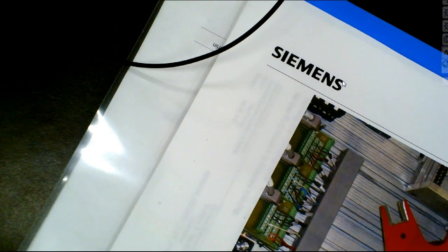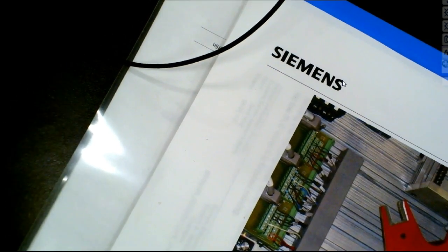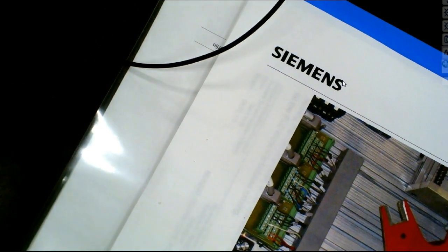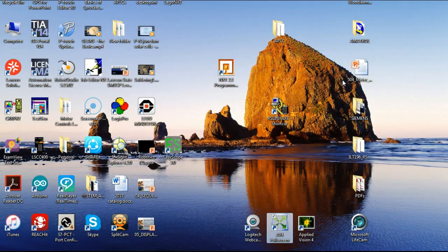Now this is a 65.5 to 1 ratio. So it takes 65.5 turns over here to get 1 turn over here. Do you understand that? Or this right here would be 1 over 65.5 of the speed that's over there. So this has a gearbox, this has a motor. Now what gears are in there, I don't know. I think I got another one over there that I might take apart later on and see if we can actually see the gears.